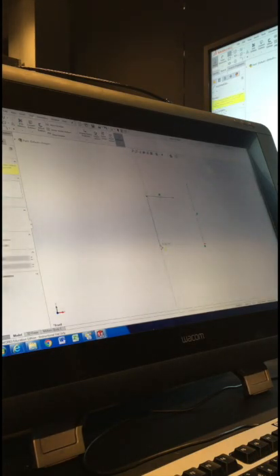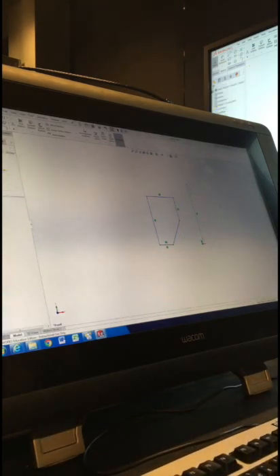And I'm just going to sketch around slowly. So automatically I've got a horizontal up the top, vertical down the side, horizontal at the bottom, and another vertical to finish off. Now if you do it in this way, a lot of those lines already have the relations added to them that you need. And that line at the bottom, the horizontal one, is coincident with the origin. So it's already got height in the right place. We now just need to add the other dimensions to it.